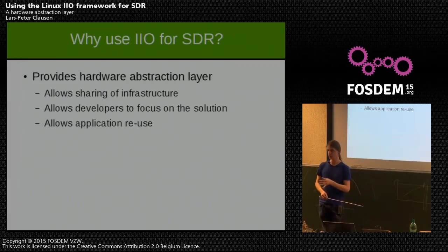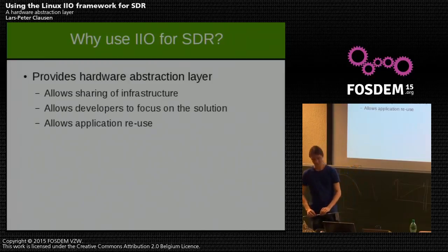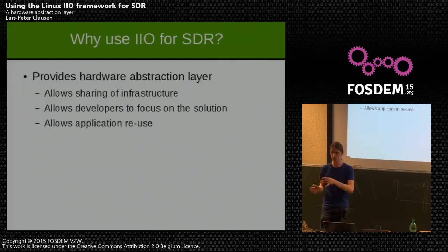Lots of the modern devices used for software-defined radio can be quite complex, with over 1,000 registers, and you need to know how to program all these different registers. And this is where the IIO framework comes in. We have a driver for a certain part, and this driver exposes a common API, and this API is shared between different kinds of devices. So you can write an application once, and hopefully it will work with this chip, this chip, this chip, without you having to modify your application at all.